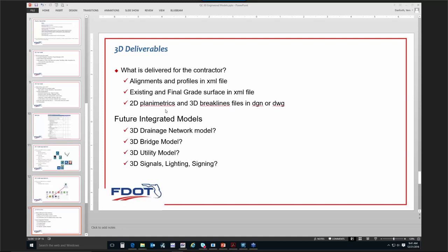And then also, I believe Trimble and Leica are now accepting the ICM files, which are what is exported from OpenRoads that does have the intelligence. That's what you can see in OpenRoads Navigator and such. That's really where the industry is moving, to where we can deliver more intelligent models for them to estimate off of and build off of. But in this interim time, these are the vanilla files that we're asking you to deliver.